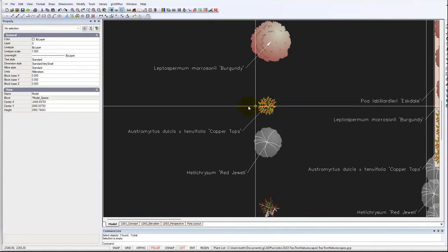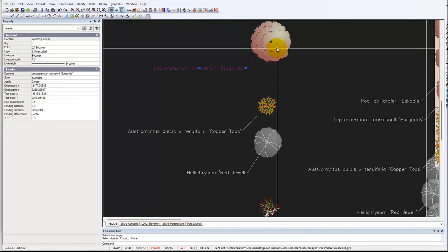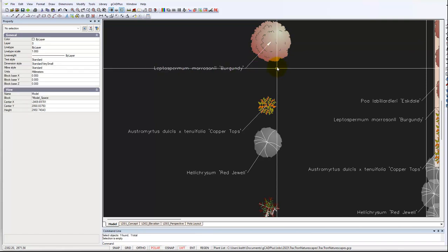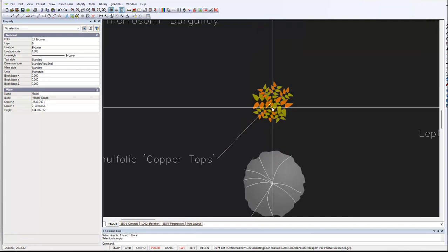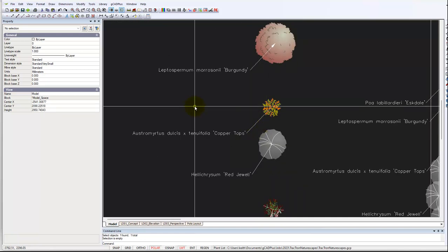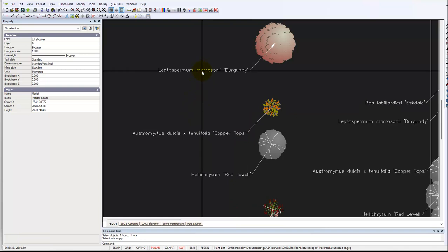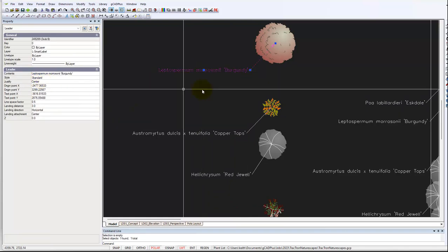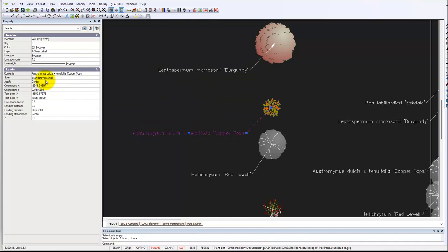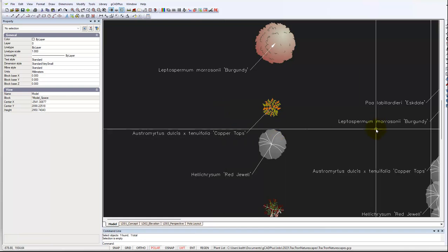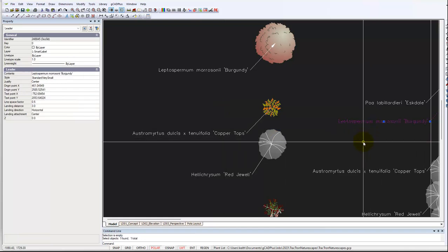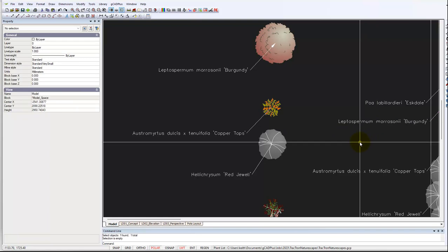You may have noticed that the leader information, the SmartLabel information here, has an arrowhead that's visible, whereas in this one I'd have to zoom in quite a lot to see it. The reason there is that there are two different dimension styles in operation. This one's a standard dimension style, and this one's called standard very small. So what most users do is they develop their own style which works for them, and the majority of the labels here are the style standard very small.